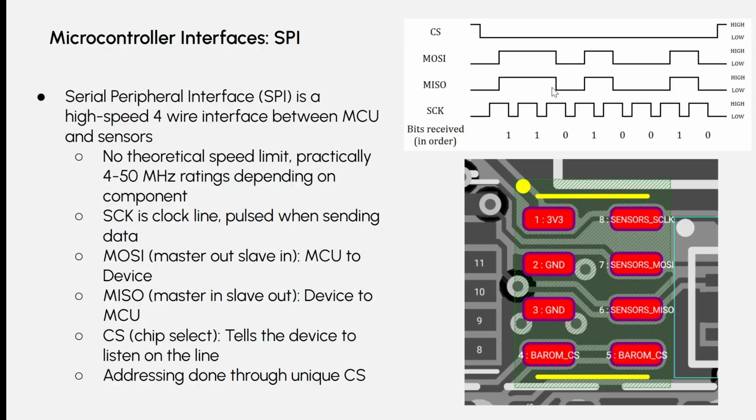Now, the nice thing is, you really should understand this protocol, but from a firmware programming perspective, you don't actually need to worry about bringing the lines high and low. It's just about when, in code, you'll call something like transmit some byte. You'll know this is what's going on. But realistically, there are libraries that handle the actual bringing high and low of the pins at a specific time.